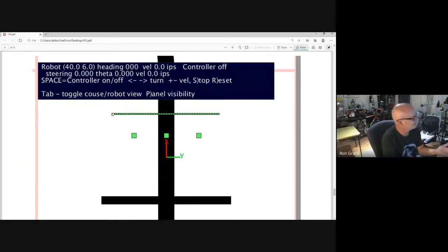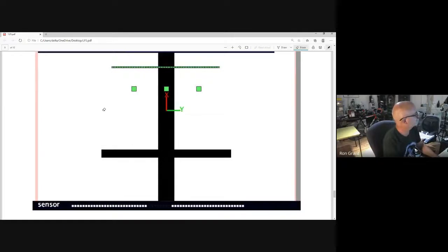In my example controller, which I'll illustrate in a few minutes, it has a simplistic program that will tell us the centroid of the line. If the line is centered as it is right now, perfectly, we would get a 0 value. And as the line moves off to one direction or the other, we get a signed value of the centroid read by that line sensor. I'll illustrate that in just a bit.